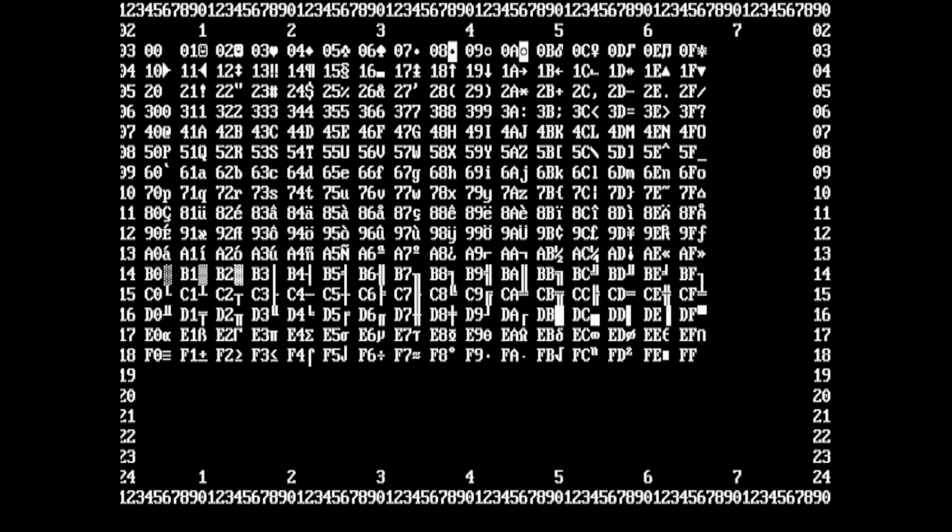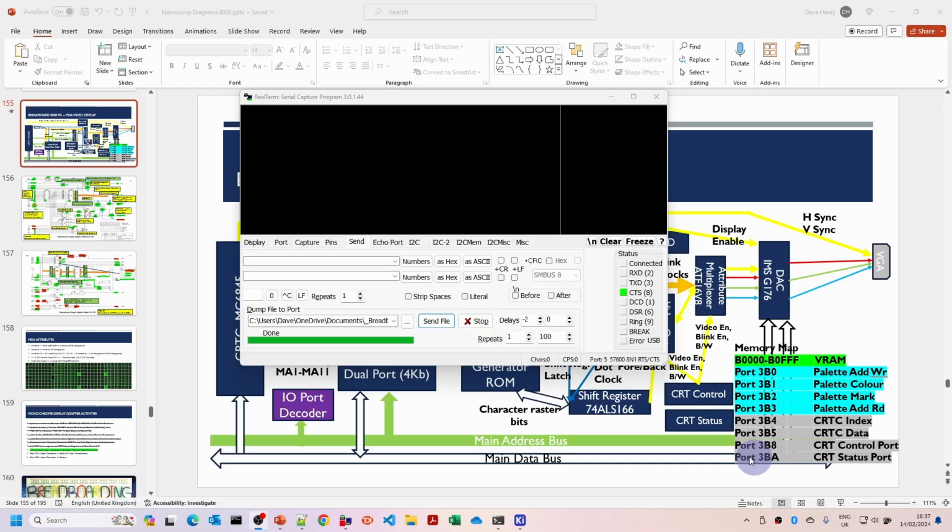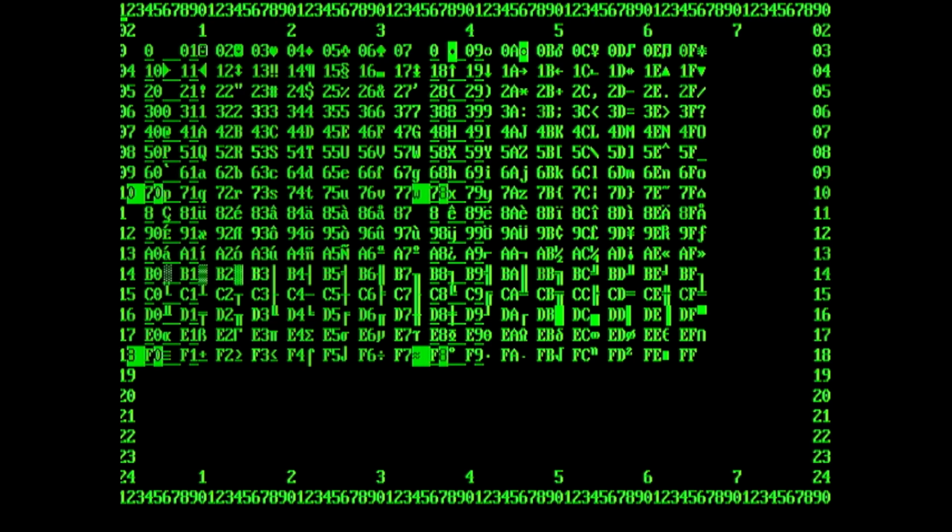So now let's try using one of the monochrome test patterns that I've got. So now I'm going to run MDA test 5, which should enable the necessary control port signals, and this will also give us green output, hopefully, in monochrome with blinking. Now I do just need to switch the video enable back to the positive one. So just going to send this down and press go.